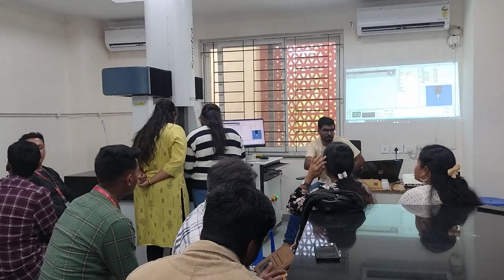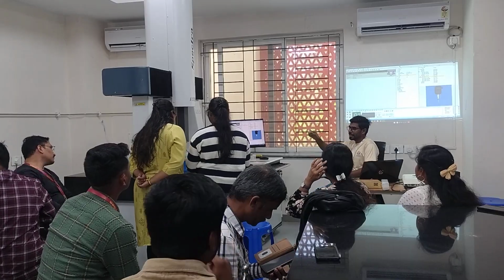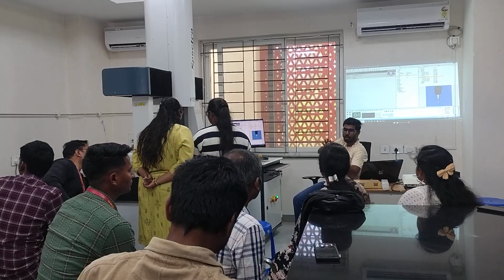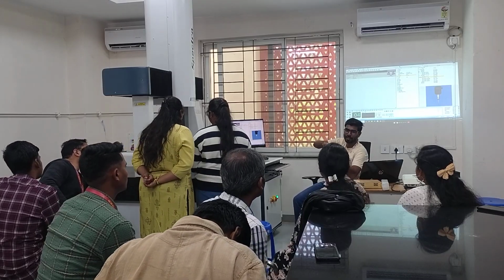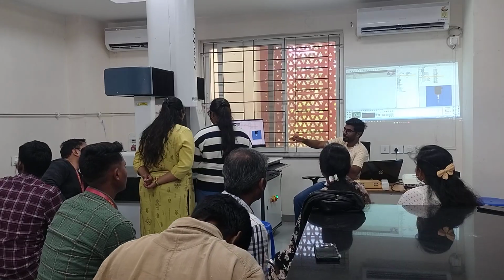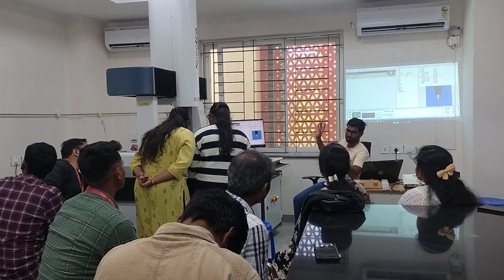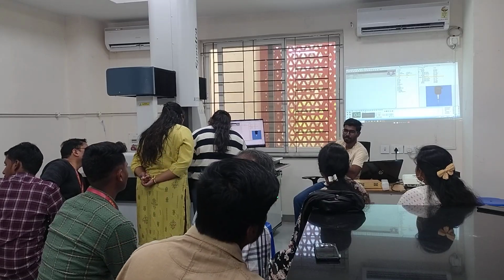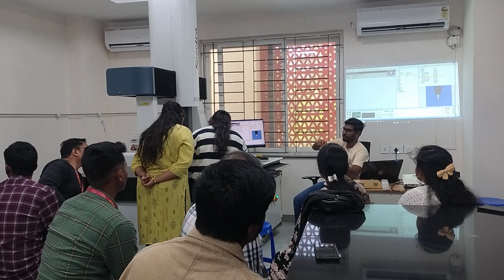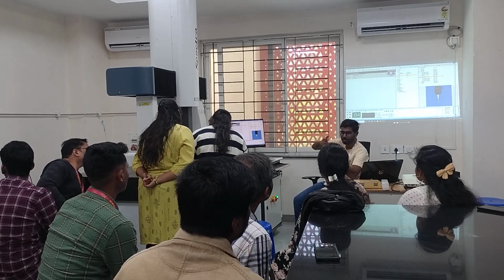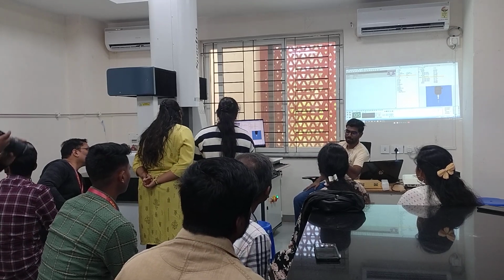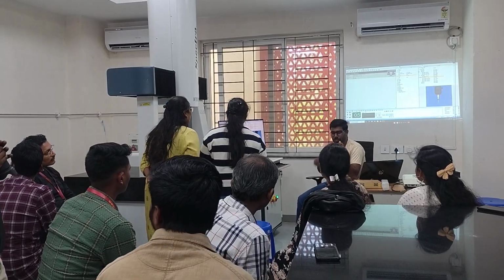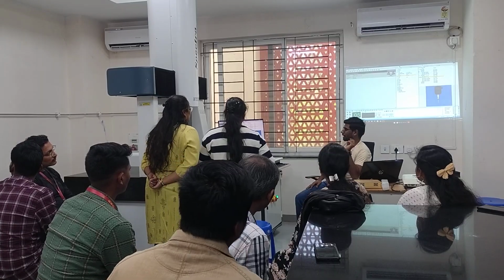So the second part we are using again and again. What happens is this is another feature. If you directly import this CAD model into this, it will automatically understand where the other features are and will program it in a manner that wherever you are doing it manually, it will automatically take CNC codes. Just place the part there, tell it through 3 or 4 probes that this is my plane, this is my plane. Automatically, for all the planes, whatever measurement we are giving, it will measure all the things and give us a report at once. So no need to repeat it again and again manually. That is what happens in assembly lines. Each and every part goes under quality control of the vendor.